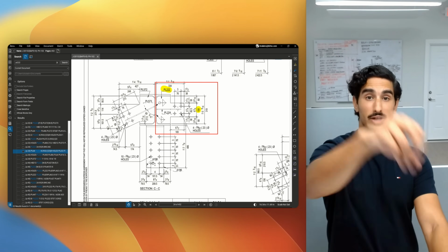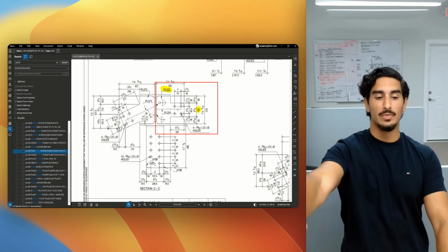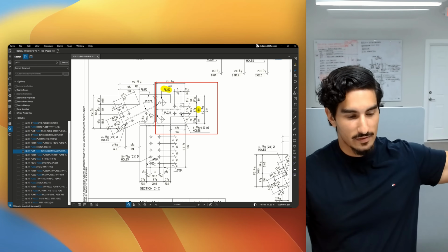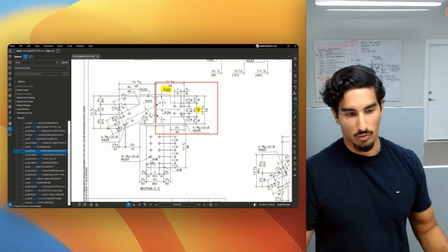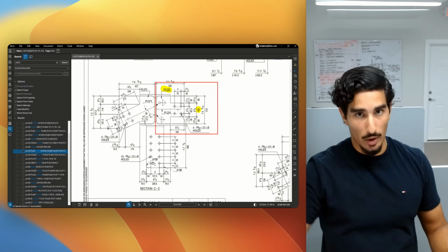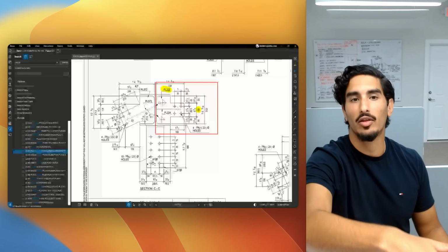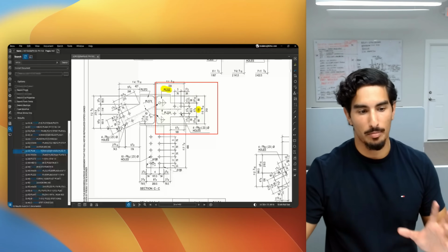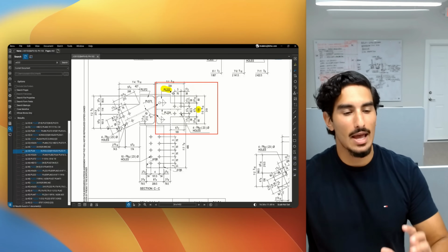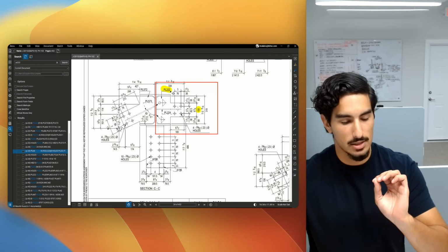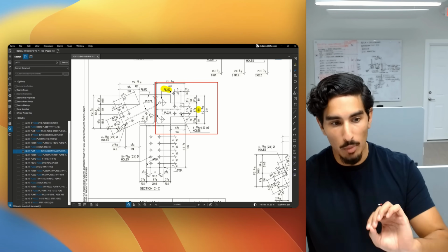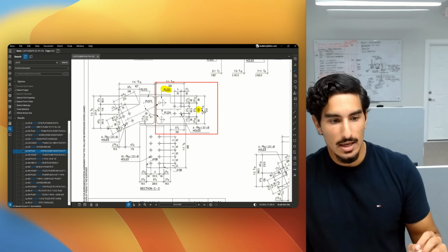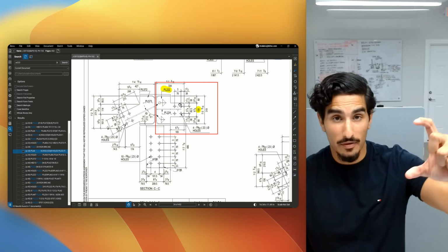This is like a bird's eye view if you're looking down at the column at this specific elevation. And the left-hand side is the left-hand beam going off at an angle. The right-hand side is an eastward beam going off at that angle. And then pointing down on the page is the south-oriented beam. So the plate that we're looking at here is PL222. That is the piece mark identification number for this plate, and the number that we're looking for is the effective width.